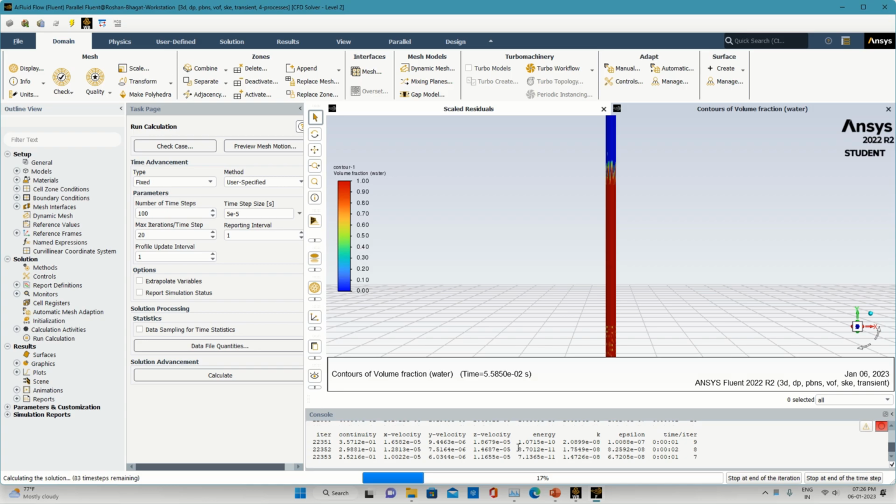So the best way is just to change the size of the mesh, go back to the workbench window, and click on the update option. But one more thing to remember is that the iteration will start again from a lower value, meaning zero. This is one drawback of the system, but if there is no other option available, then this process can be utilized.